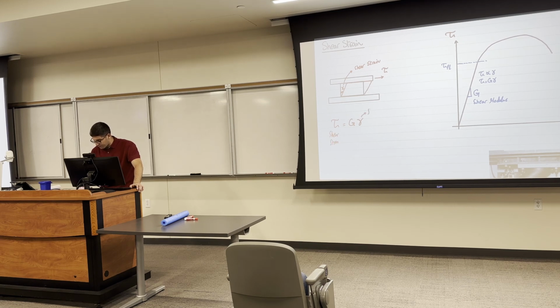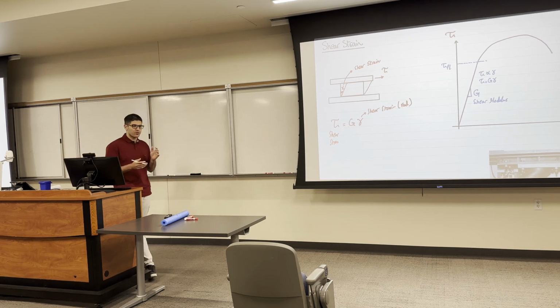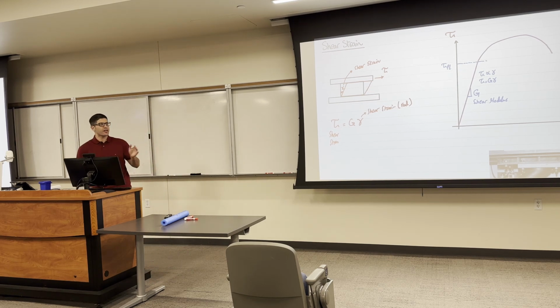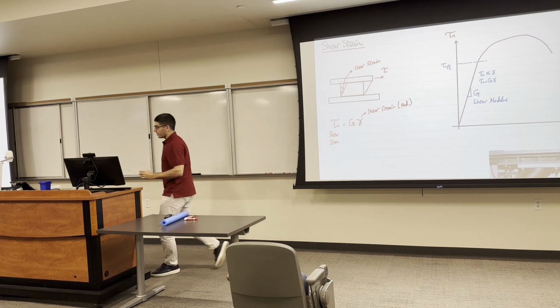This is shear strain. And the shear strain here, the units is in radian, okay? Before we had the normal strain, it was inch over inch. Now we have the shear strain in radian, and you all can tell why, because it's an angle, okay?